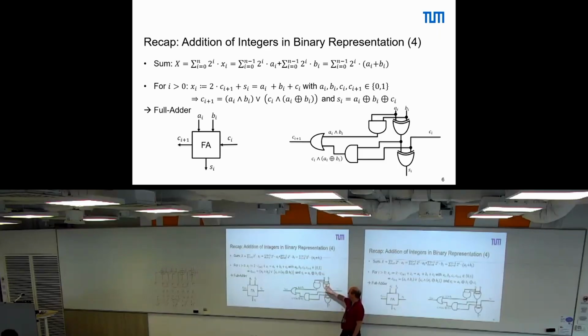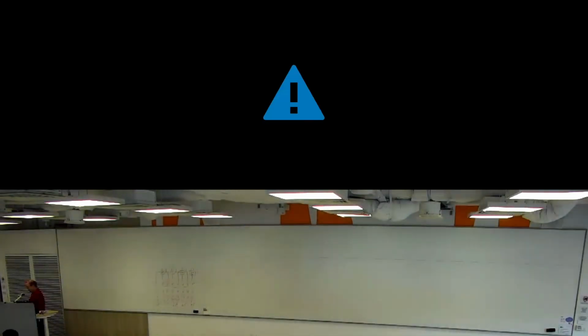So overall, if we go from a full-blown adder to a specialized counter structure, we have the benefit that we save power, we save time, we save area. Of course, we only save area if we do not reuse the adder anyhow for something else. So most of the time, any digital circuit has already somewhere an adder.